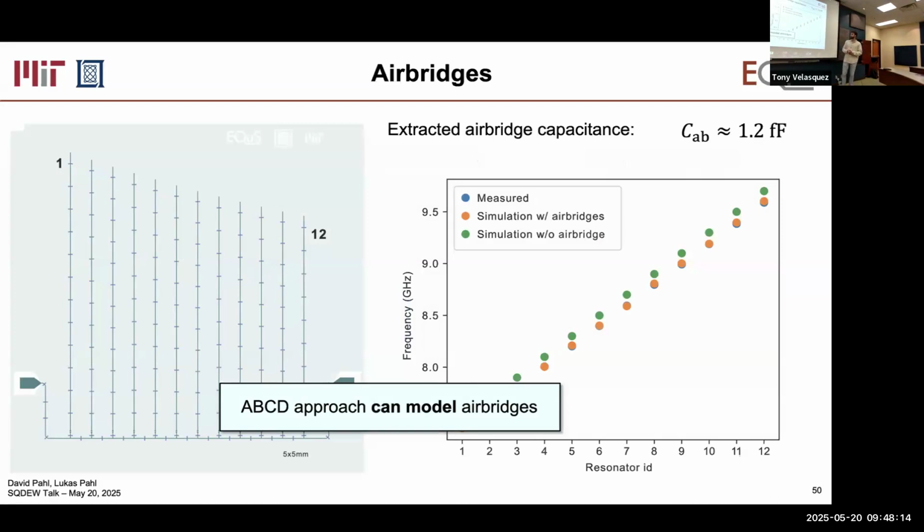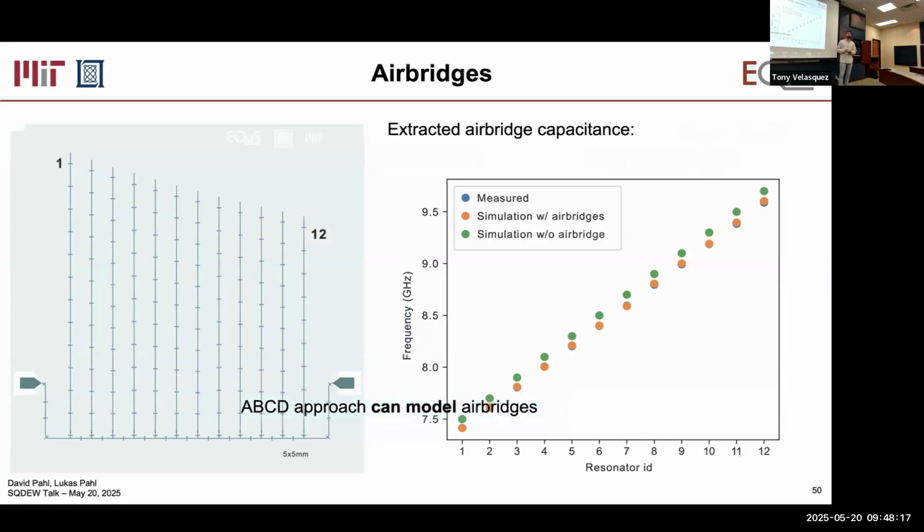Yes, for sure. So wire bonds, does everyone know what wire bonds are? So what they are is the signal that doesn't just end here on this pad. In fact, in reality, this chip is embedded in a PCB that has a cutout where this chip fits in. And then there's a piece of metal, a wire that sticks to this pad and then sticks to the CPW on your surrounding PCB. And that piece of metal actually adds inductance. So it looks like series inductance. And the effect can also alter your physics in your device. So you want to simulate them too. I also have test devices that do that. I won't talk about them here.